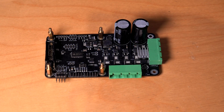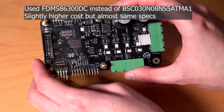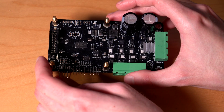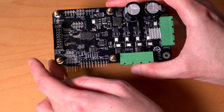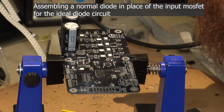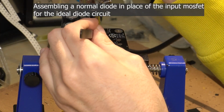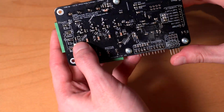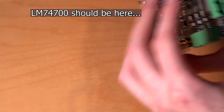Unfortunately, a lot of parts became unavailable again for this version, so you see different MOSFETs on these boards, and I also had to find replacements for many other parts as well. And unfortunately, the LM74700 ideal diode controller used in the previous version also had to be replaced for these prototypes with a diode instead of the MOSFET. The pad of the LM74700 was left empty in this version.